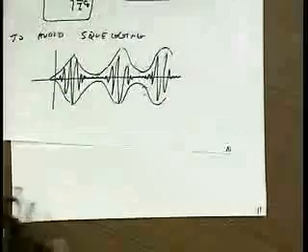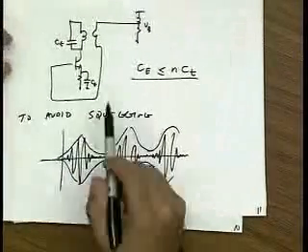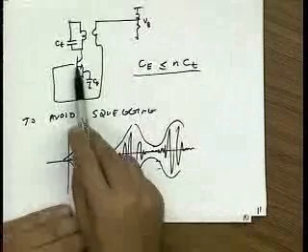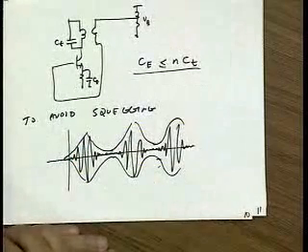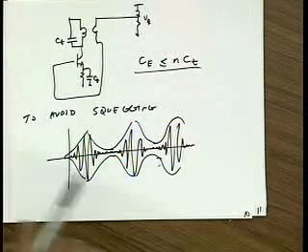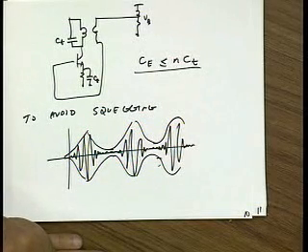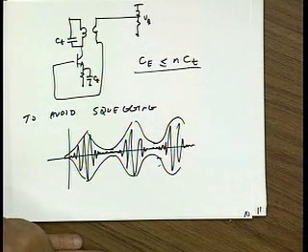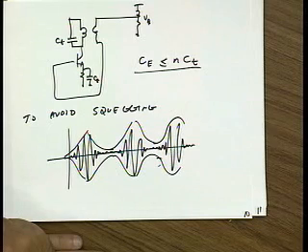Okay. Yeah, it's definitely the RC time constant with the GM of the transistor, yeah. Kevin? When we're growing in amplitude, that's when the loop gain is greater than 1, and when it's falling it's less than 1, right? That's right. Shouldn't GM be a continuous function of V out, so eventually the loop gain will be 1?